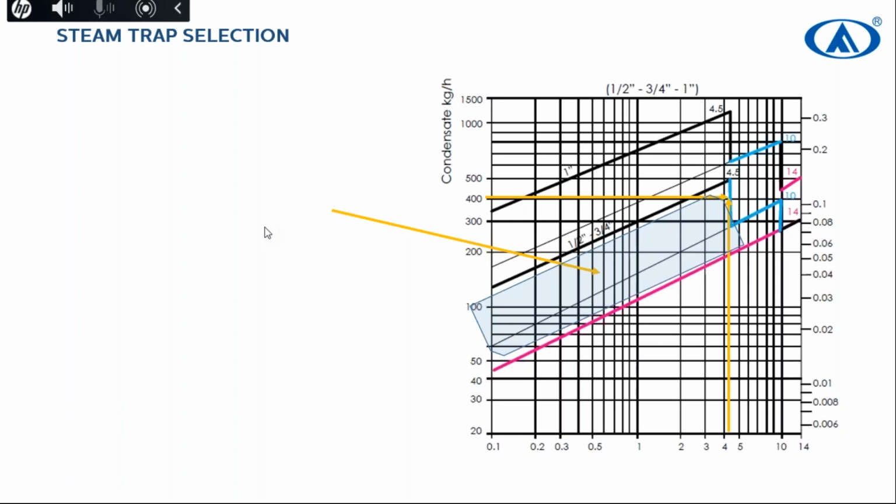For thermostatic, HTT6, our hygienic thermostatic steam trap, is suitable. TKK42 and 41 are suitable. For float type, SK61 is suitable, you can use. And for others, you can use TK1A or TK1. And what about the heat exchanger of the beer industry? I also answered, I guess. You need to use FDA certificated, with food certificate, for brewery.